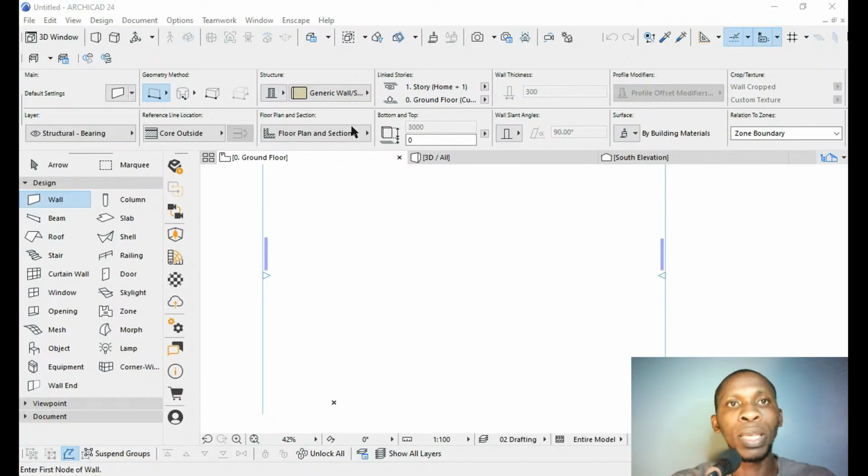Let's click on floor plan display, and instead of using projected, you're using symbolic cut. What this means is that you are viewing a section. When you have the window sill and half of the wall, the floor plan is like cutting through the center part of the building. That's what the floor plan means. You're seeing from that center part downwards, you're seeing a plan. So if you have furniture inside there, it will show on plan. That's what it actually means.